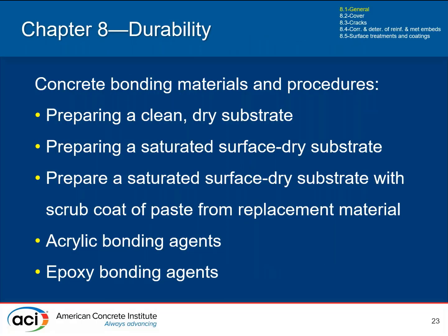And then bond is the other aspect that goes into it, because as I mentioned, they're going to have a different history. They're going to be different materials. Even if you go to a substrate and figure out exactly what was used to produce that concrete and use the same for your repair material, it's going to have a different history, a different age. So they're going to behave differently. So to get them compatible, that's where the bond comes in. That's something you need to think about. Okay, that overcomes the differences in properties and compatibility. So bond is an important aspect.